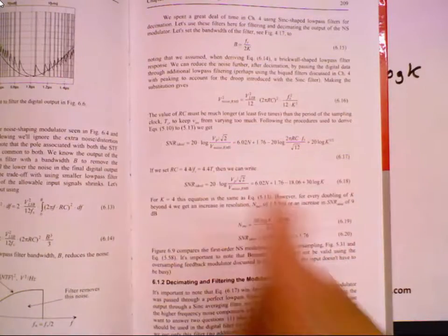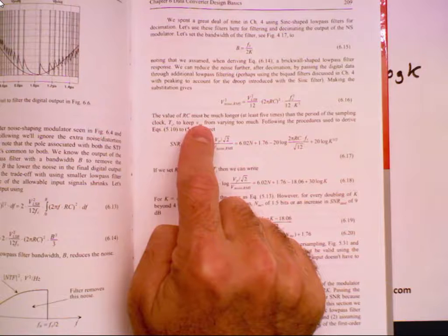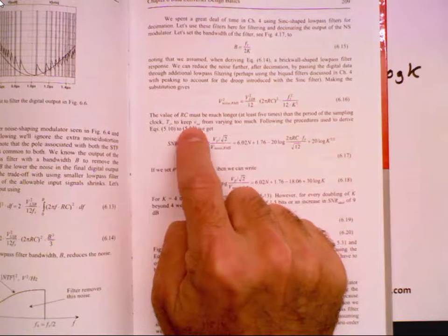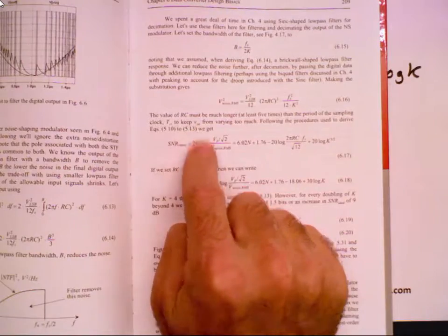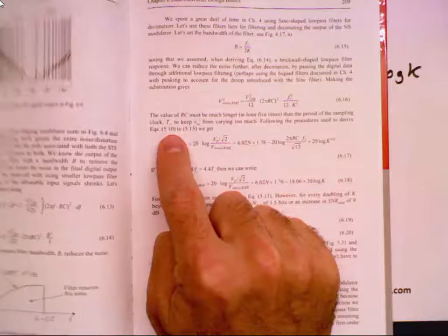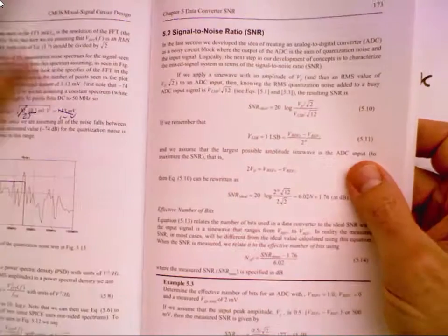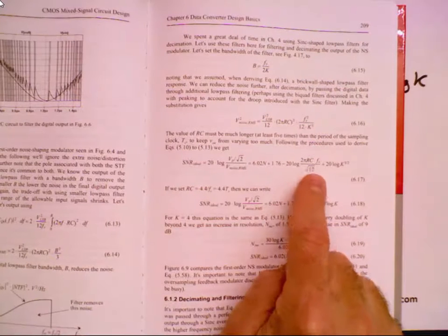So let me repeat. In active integrators, V-int is 0, so that's not an issue. Okay, and I'm trying to make this generic for the generic delta sigma case, okay? If I use slow-moving signals, then I don't have much variation in V-int anyway. Okay, so if we go back and look at these discussions of 510 and 513, yeah, that's just following that. So why did I use 4.4 though?